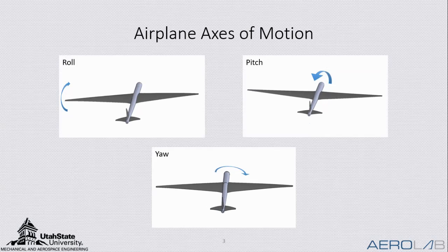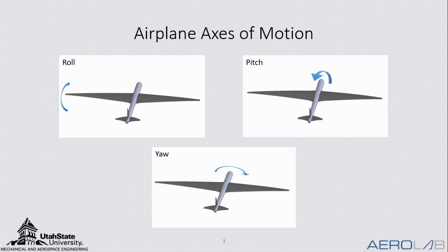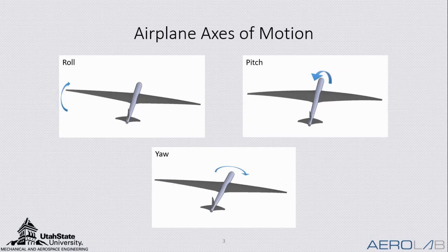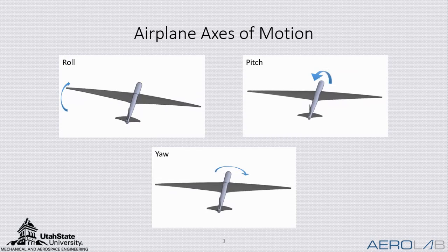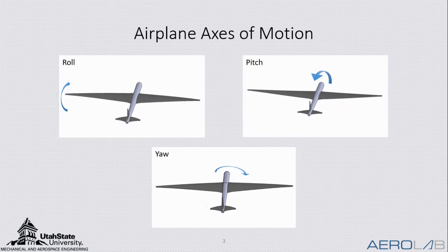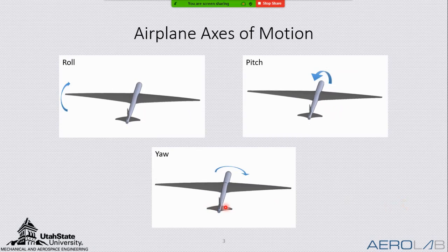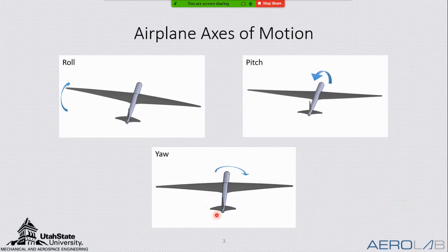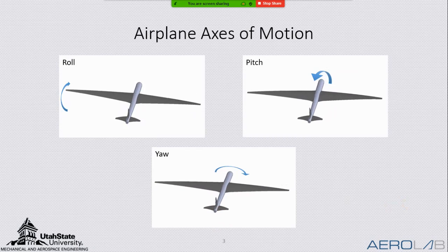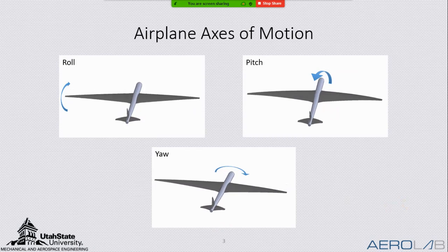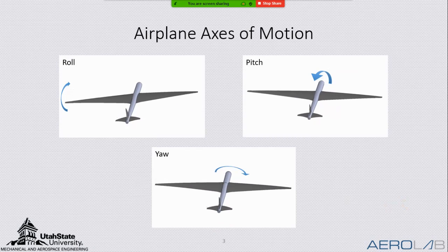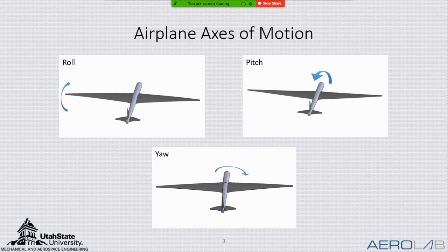First, I want to focus on this: there are three principal axes of motion on an aircraft. The one I want to focus on is yaw. So a flying wing aircraft does not have this vertical or horizontal surface that you see back here. That's the tail of the aircraft. And the purpose of that is to make the aircraft more efficient, to get rid of those surfaces which cause an increase in total drag on the aircraft.